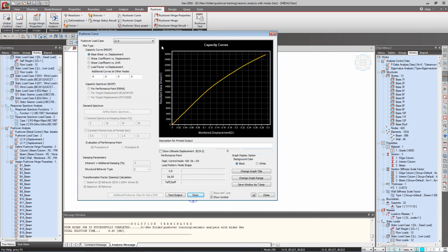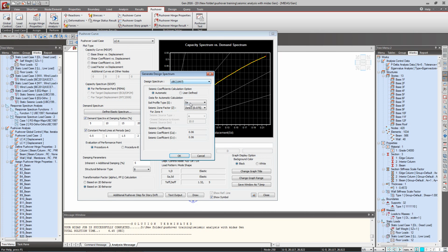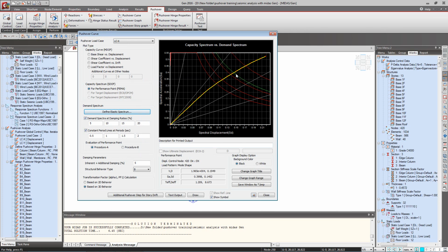The benefit of the capacity curve is to get the performance point. The performance point can be obtained again. As you can see, it will be unchanged as C zone 4. We have used the performance point to get the target displacement. So we have got this in here, but the structure is not supposed to be designed only for this displacement, but for this particular displacement. So we'll be checking the capacity of the structure now for the last pushover point.